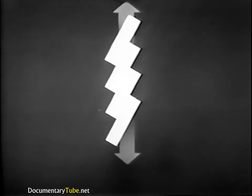In tension, the crystal is stretched parallel to the axis of tension. In compression, the crystal is stretched perpendicular to the axis of compression. It is by this process that the metal grains become elongated and uniformly oriented when an alloy is cold worked. Essentially the same action is involved in the plastic deformation of the polycrystalline grains composing an alloy specimen.